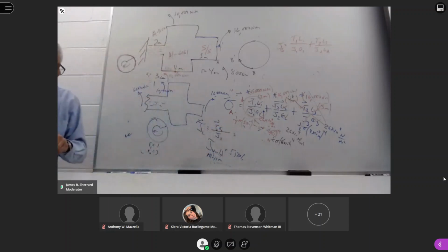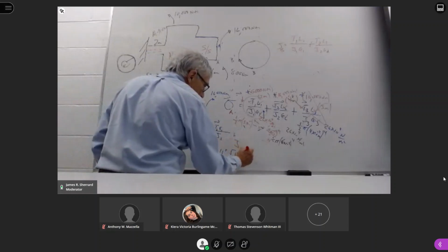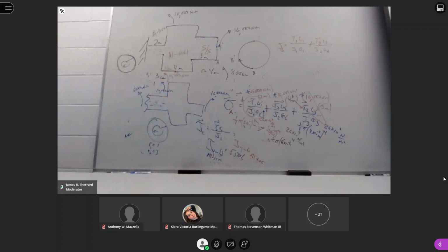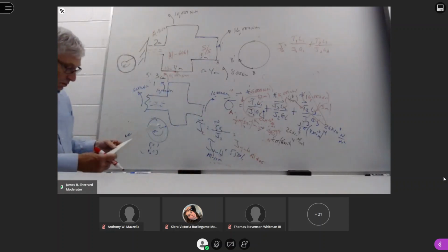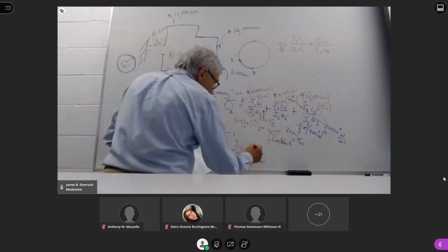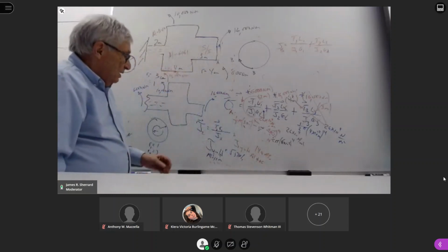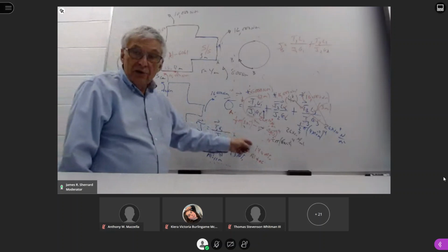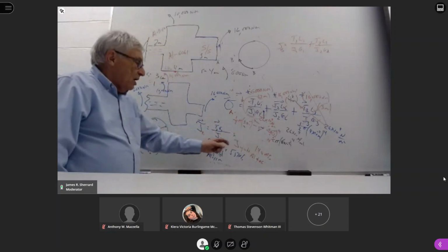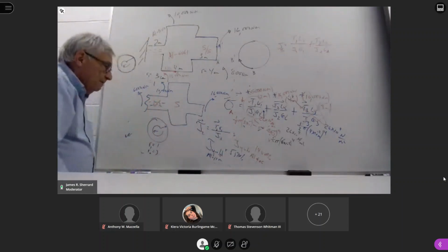So that's going to be that same value, except now we're comparing this value to the yield for aluminum 6061, and that value turns out to be 140 megapascals. So if the value we calculate for region 2 exceeds 140, it's unsafe. If it's less, it's safe. And I remember that the value we calculated was less than 140. So this is safe, this was unsafe.